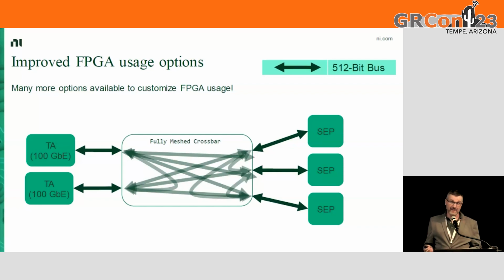This was necessitated, there was public demand for that, but also for the USRP X440, we really had to do this. In the past, if you built a custom design, you had the option to choose a bit width, which sort of gave you a maximum available bandwidth. The maximum bit width that we support on our devices is 512 bits per bus. And if you want to do 100 gigabit Ethernet streaming, that's what you need, because otherwise you can't shift enough data over the available buses.